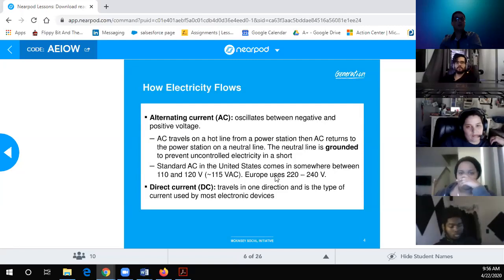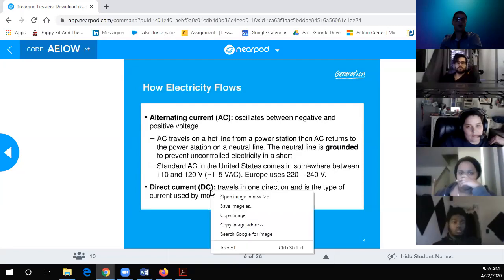You will blow up the computer if you didn't have what these modern computers have, which I've already seen happen in the old ones. You will mess up the computer. But nowadays, they have that little dip switch that I showed you in the first slide, that little red dip switch. And usually that will pop to the right voltage if it's the higher voltage. Usually, if it has the auto one. If not, it just doesn't turn on, and you must go to the back of the computer and hit the little dip switch to either 220 or 110 to the right voltage.